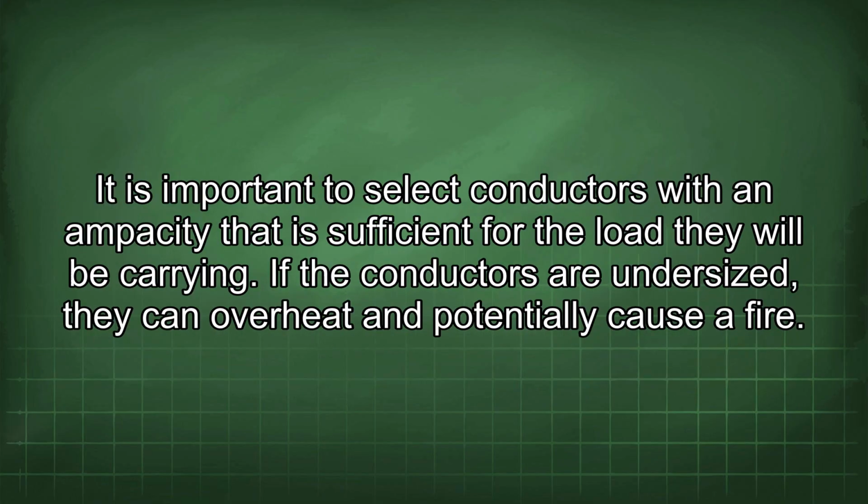It is important to select conductors with an ampacity that is sufficient for the load they will be carrying. If the conductors are undersized, they can overheat and potentially cause a fire.